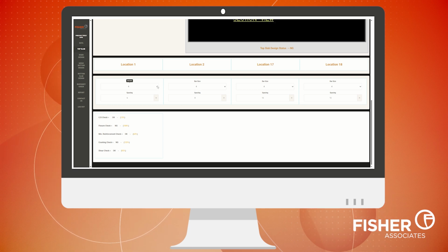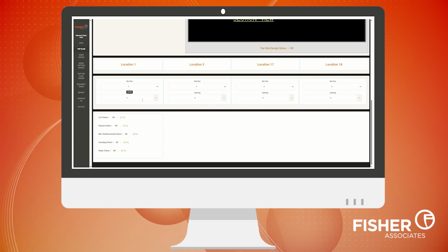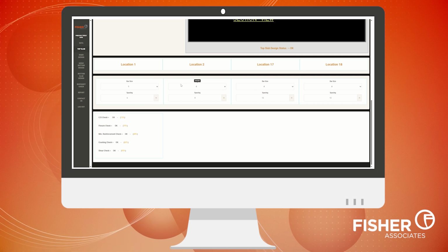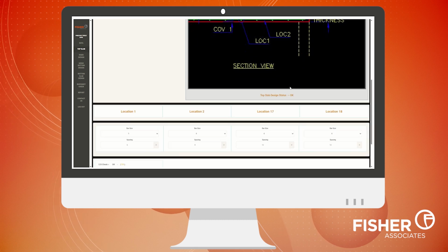I am going to bump your reinforcements. You will now see that the NO text has changed to OK. If you scroll back up to the bottom of the plan, you will see OK next to the top slab design status text. You can now move on with your design.